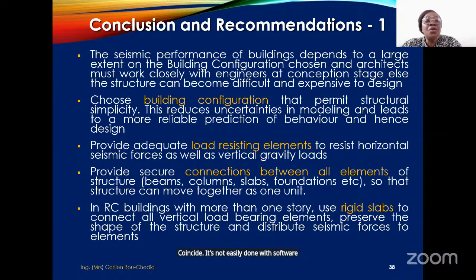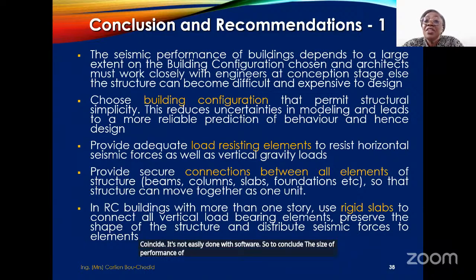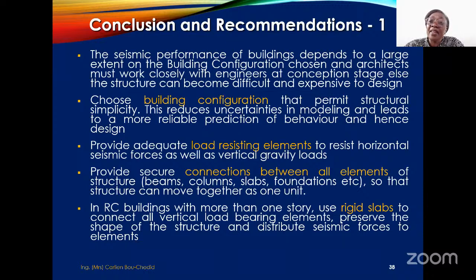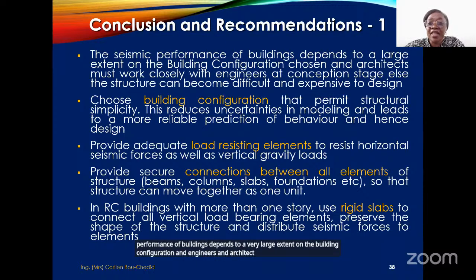So to conclude, the seismic performance of buildings depends to a very large extent on the building configuration, and engineers and architects must be working together at conception stage, else the structure can become difficult and expensive to design.